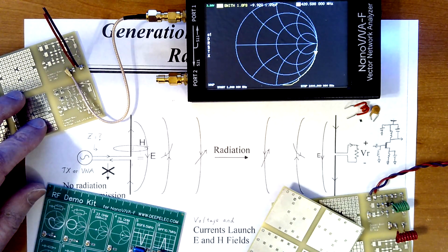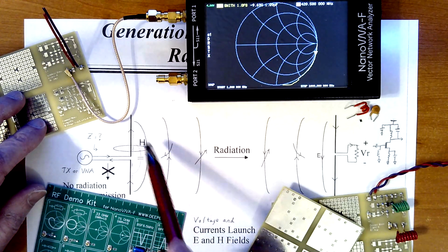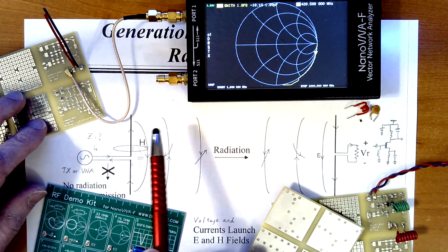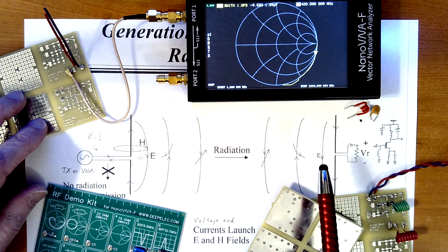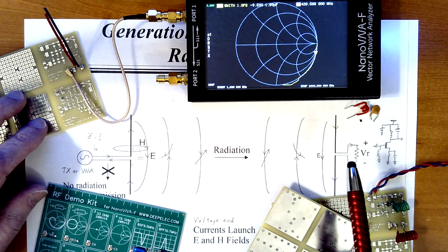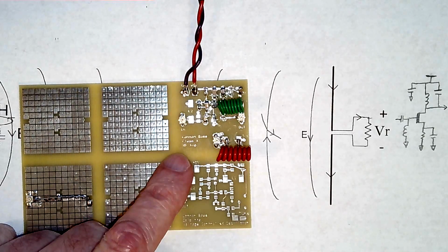What antennas fundamentally do is take a voltage or current excitation and turn it into propagating electric and magnetic fields. And those propagate out away from the source and eventually get over to a receiver where they induce currents in a receiving antenna, which is fed to an amplifier and filters and all of the other radio electronics.